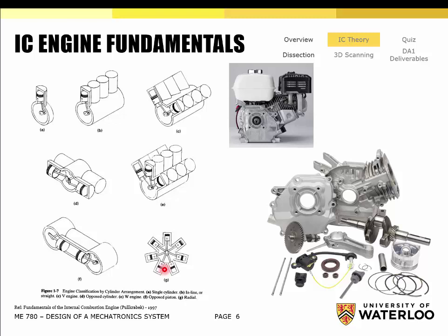Vibrations, that's one thing that unfortunately we can't go into a ton of detail on in this particular lecture, but each of these crankshaft designs has a different harmonic balance and a different torque signature profile depending on how each of these cylinders is firing. Okay, so what you're saying is very true. It can improve or make worse the vibrational aspect of the engine. You think that, okay, this engine is just firing every 1, 2, 3, 4, 5, 7, so 1/7 of 360 degrees. It's just firing constantly like that, so it's a very equal torque output. So that is true. Yes. Anyone else?